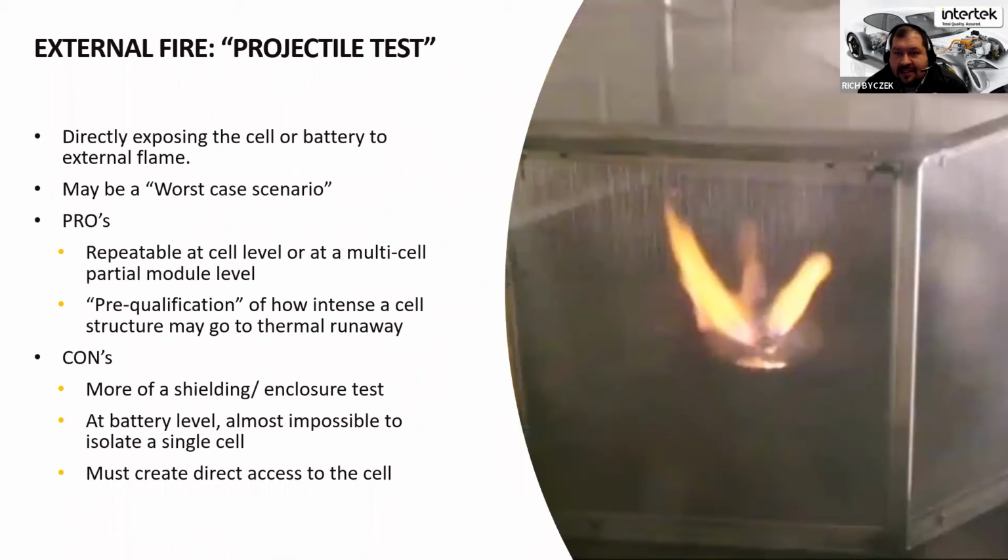External fire, the projectile test. A lot of times this is used as a way to essentially pre-certify individual cells. If I expose that cell directly to external fire, how bad of a reaction do I get from that cell? So exposing the cell and looking at how it performs under external fire exposure helps me to determine whether or not I need to do a secondary test at the modular battery pack level.